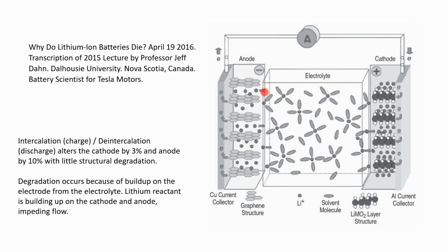But what happens is that barrier between the electrolyte and the anode develops particulate that then plates the anode and fills in the holes inside the anode that the ion could be squeezed through. And as soon as those holes get covered, the ion can no longer come out of the anode,